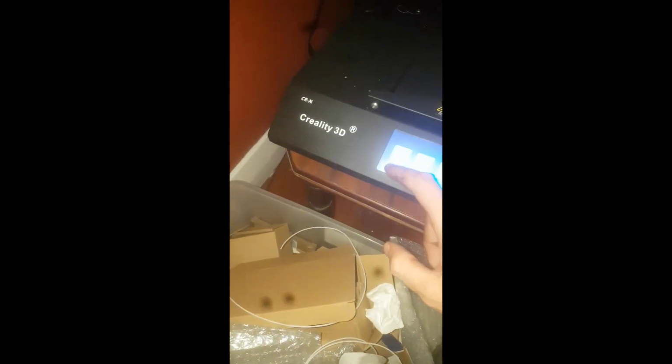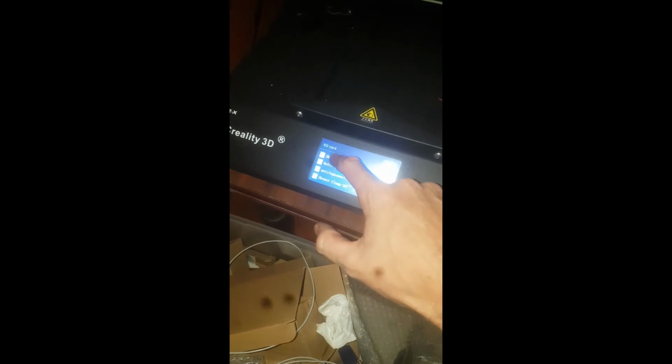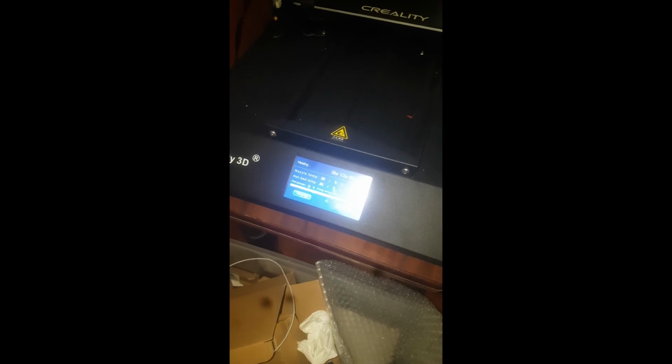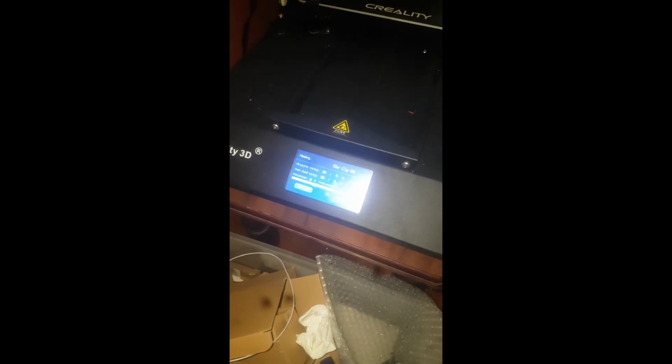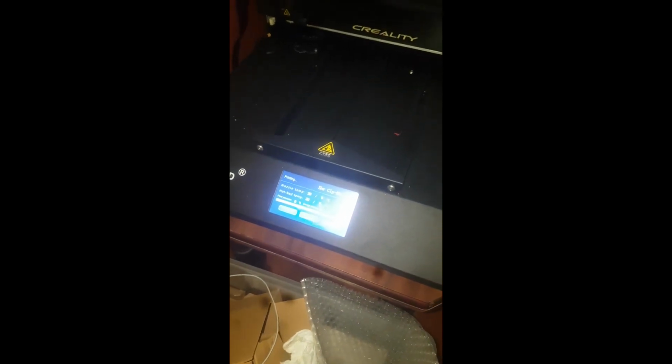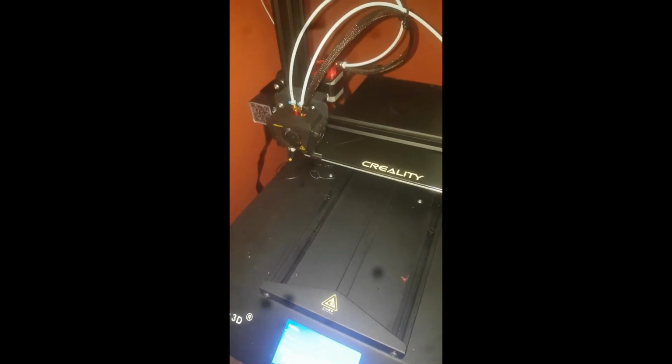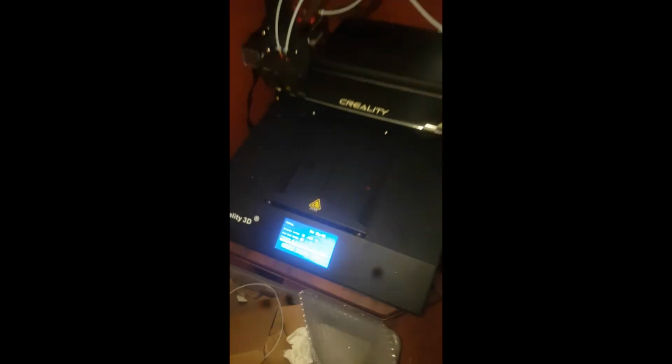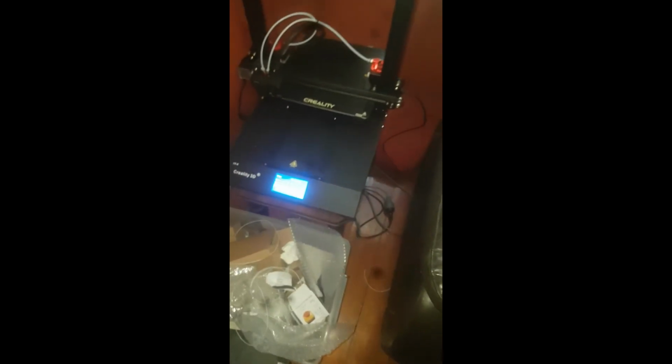And it's just as simple then as turn it on to print. Select the file, we go print. There's some temperatures there on the display, and what will happen now is the machine has to heat up to its temperatures, and then it'll begin doing its thing. So it just homes its head first, into the corner. And you can see now it's going to really slowly start ticking up. It's going to get to 200 degrees Celsius on the nozzle, and the bed's got to be 60 degrees for this material. We come back a little bit later. It takes 5-10 minutes to heat up.